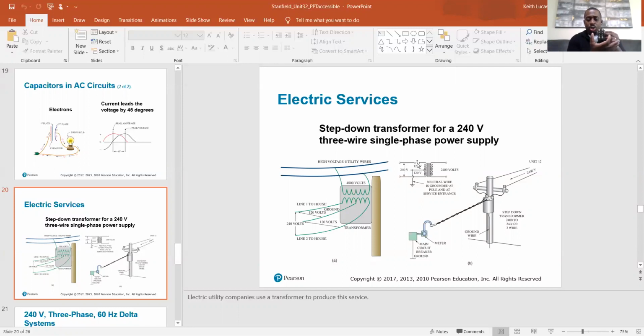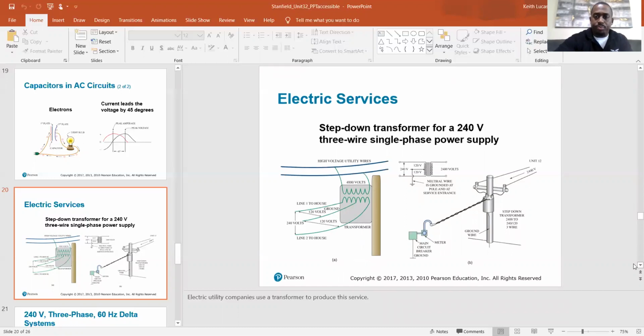And not until your 24 volts energizes your coil saying, hey, we want the AC on, go ahead and close this. The 24 volts closes this, the 240 actually runs the condenser. So operating voltage, control voltage. You have both, and that's the whole point of having your transformer in your system. That's where your low voltage is coming from.